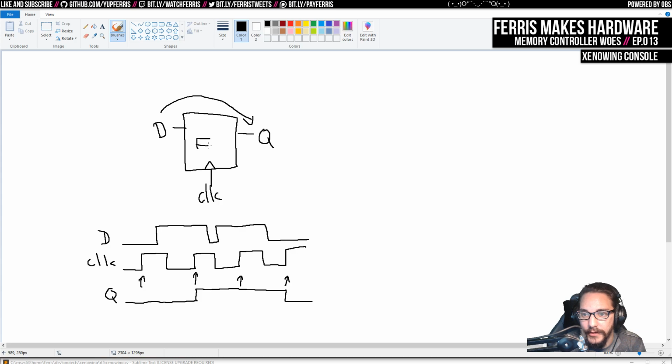So this is our flip-flop or our register. Register is typically a D flip-flop, which has this kind of interface, and sometimes you also see the inverted Q just already available there, but you could also get that by sticking an inverter on this. So it really doesn't matter how you want to set that up. But anyway,